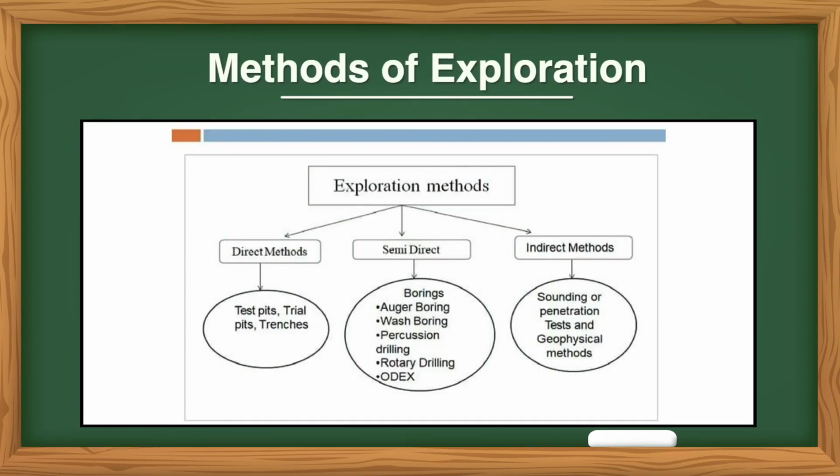So, direct methods include test pitting, trial pits, and trenches. For semi-direct: boring, auger boring, wash boring, percussive drilling, rotary drilling and Odex. The third one is the indirect method. In indirect methods, there are penetration tests and geophysical methods.